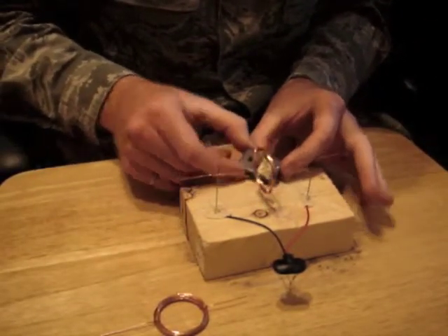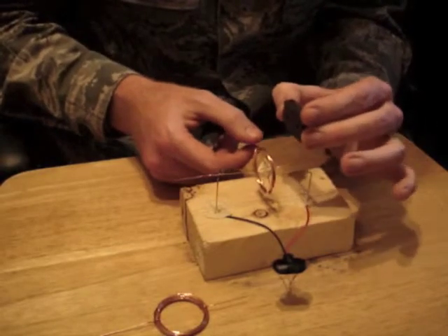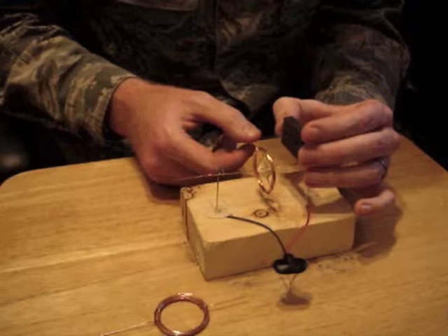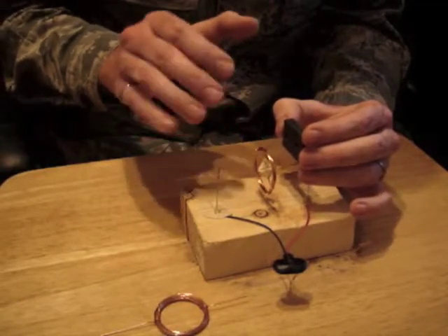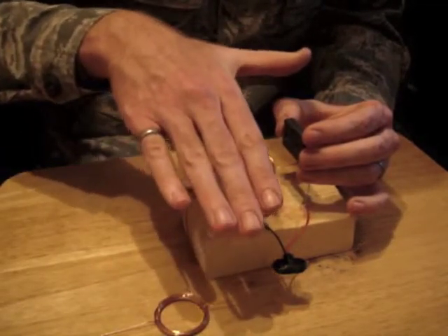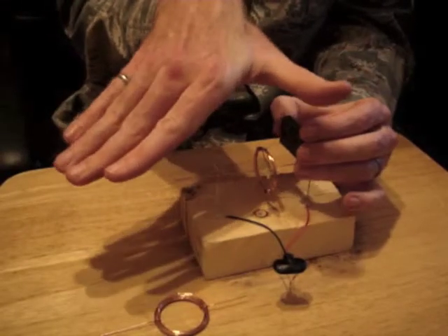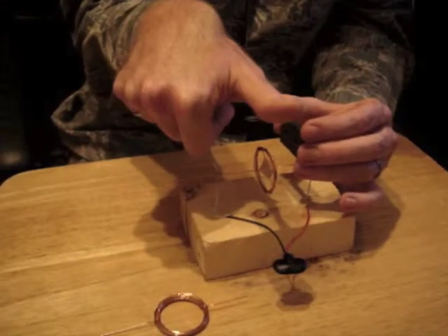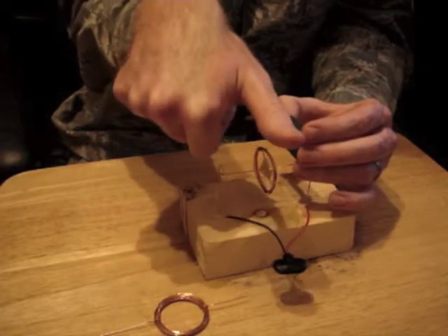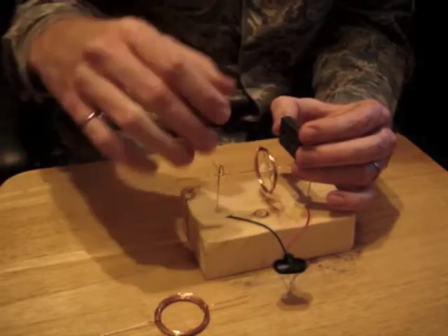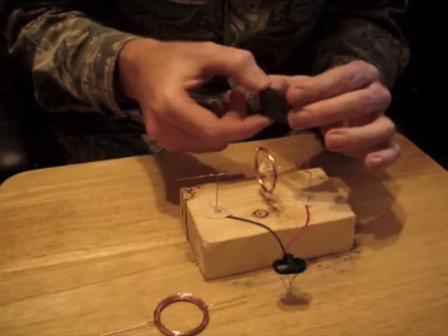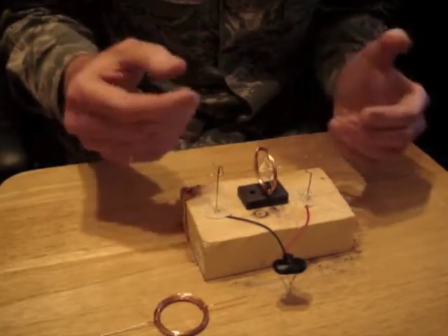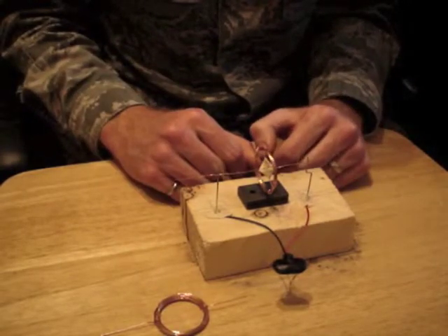And then in the final configuration, we move the magnet over to the right side, and the current flows along here. Putting the fingers in the direction of the magnet and curling them gives you a resultant force here. But again, no rotation is going to happen in this case because there's no kickstart to make the motion happen.